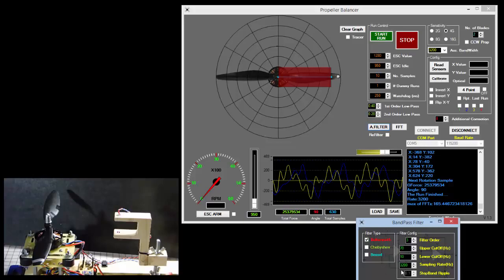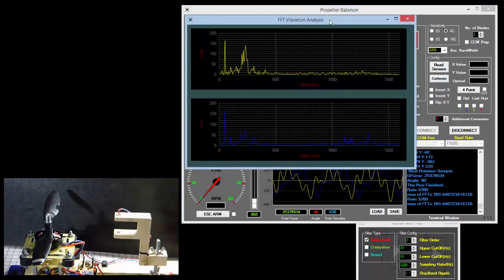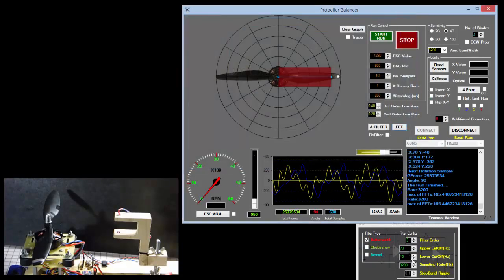And as you can see here, these are bandpass filters, which basically allow us to isolate a particular frequency. So again, knowing that the component we want to isolate is around 50 Hertz, what we can simply do is go here, and as you can see by default, we can leave it at that, because between a lower cutoff of 10 and an upper cutoff of 70, that includes the 50 Hertz component.